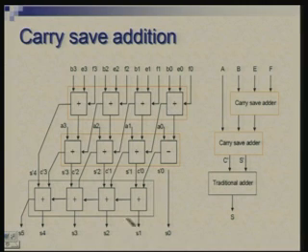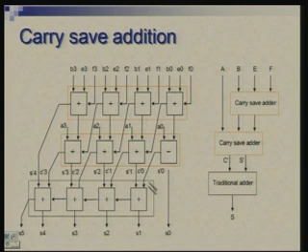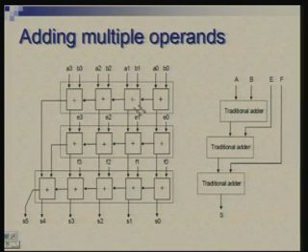One more thing which can be done here is that you can replace the last stage with a carry look ahead adder. See, a carry look ahead adder is more expensive, but faster. We have seen that you have to put extra logic for carry computation. So, we can afford to have one of these adders, that means the last adder, as a faster and expensive adder, and then effectively the delay will be less than 6. Whereas in this case, if you were to speed up, you would have to speed up each stage to make sense, and it will be much more expensive.